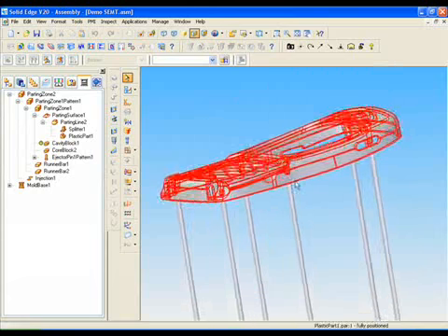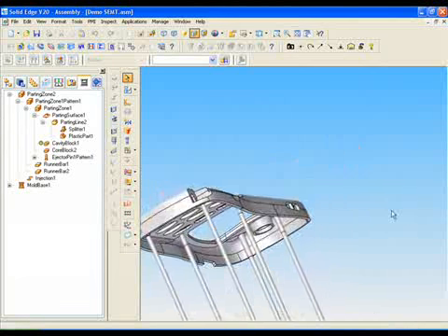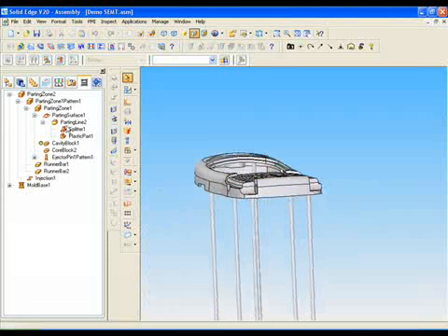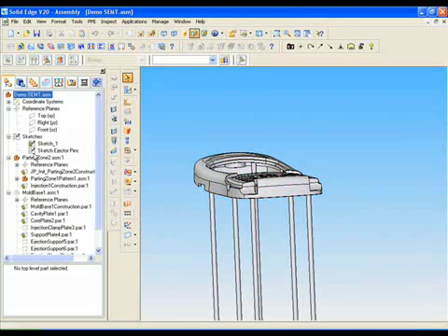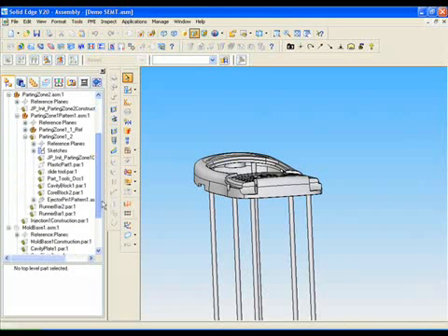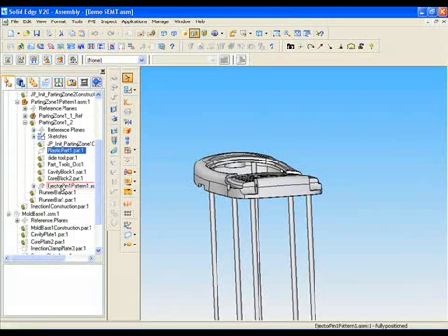The details in the part where the ejector pins touch are now clear. As the sketch to position the ejector pins was created by including edges of the part itself, if a change is made on the part, it's propagated to the associated sketch and, therefore, to the ejector pins pattern.